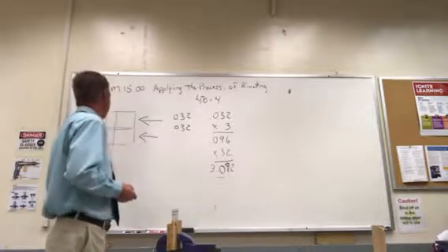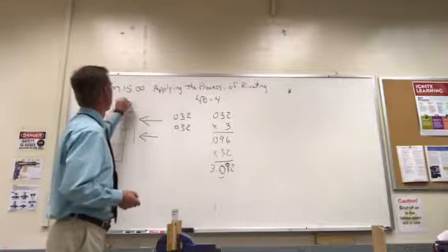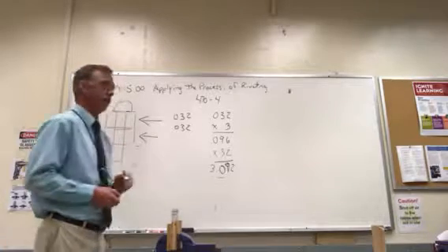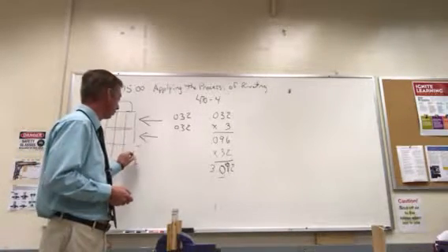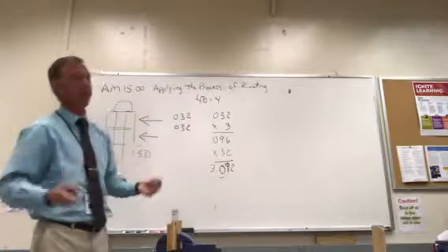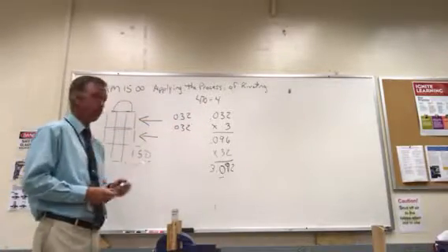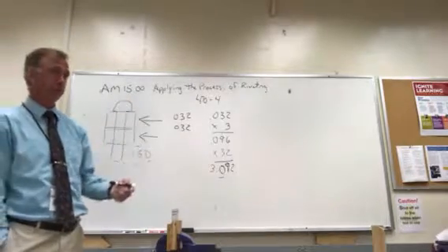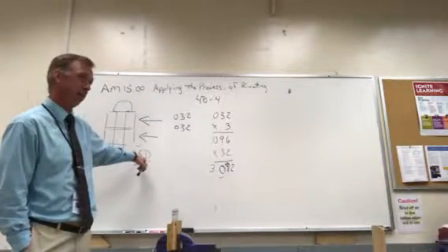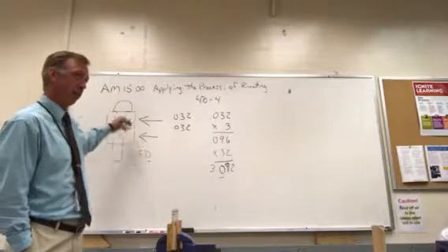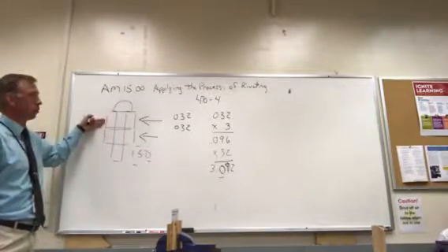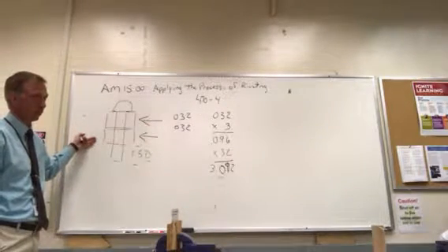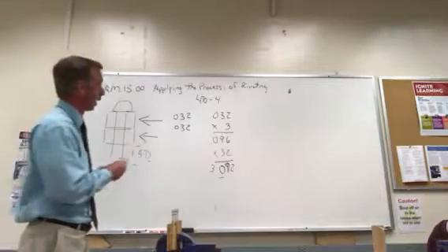Now I need to know the length of the rivet we're going to be working with. What's this measurement that we have right down here? 1.5D, which means if we're working with the diameter and it's 1.5D, this is why we have to find the diameter first, because I'm multiplying it by that. Trey, you good with that? Wonderful. 32 thousandths. You got the calculator? Add those two together.